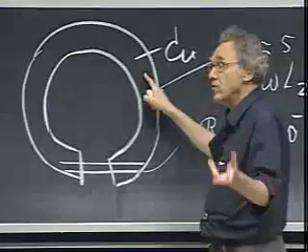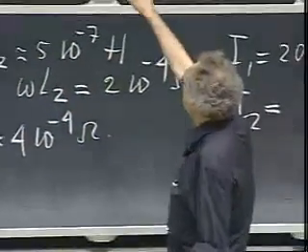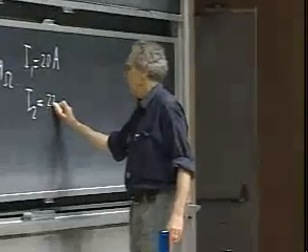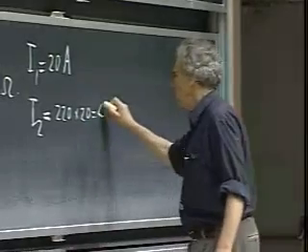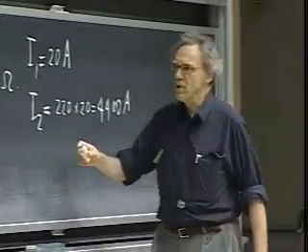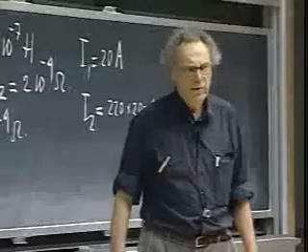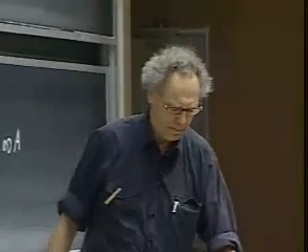So I have the same ratio N1 over N2 that I had before in that experiment when I did N2 equals 1. I don't expect that this is going to be 220 times 20 amperes, which would be about 4,400 amperes, because I am really not in the domain that R is much smaller than omega L. But I probably get 500 to 1,000 amperes.